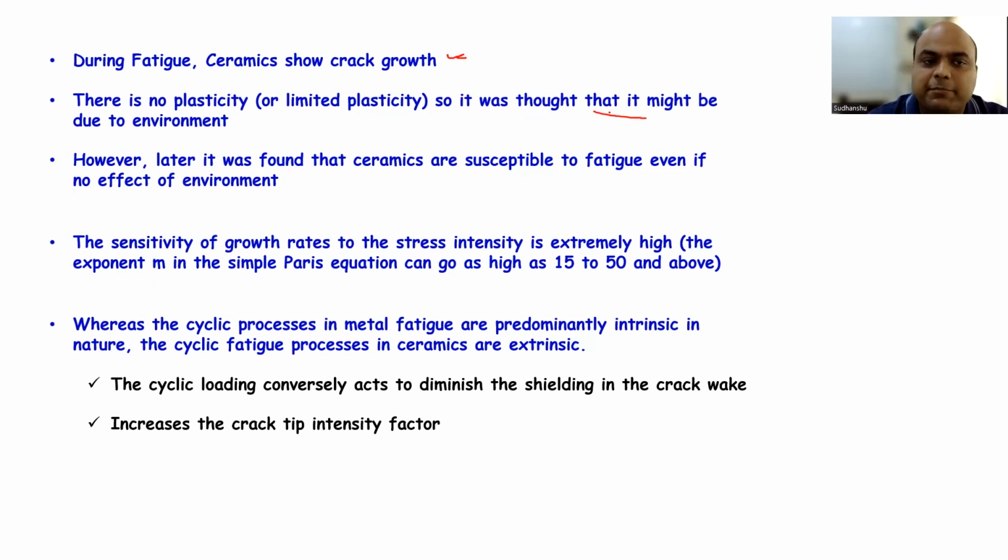So it was thought that whatever you observed in terms of the crack growth in fatigue might be due to the environmental effect, right? However, later it was found that ceramics are also susceptible to fatigue even if there is no environmental effect, okay? And the sensitivity of the crack growth to the stress intensity is extremely high. Okay, so the exponent m in the Paris law, if you remember, right? It can grow to a very high value, 15 to 50 or above, as compared to metals where it was 2 to 4 in an alloy, right?